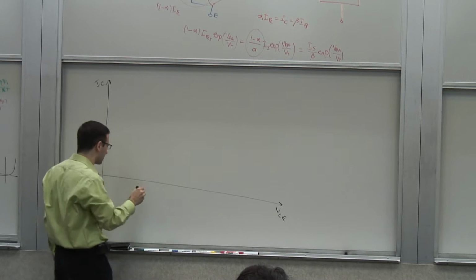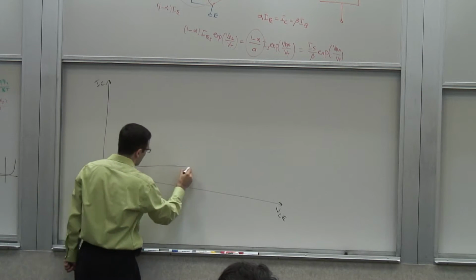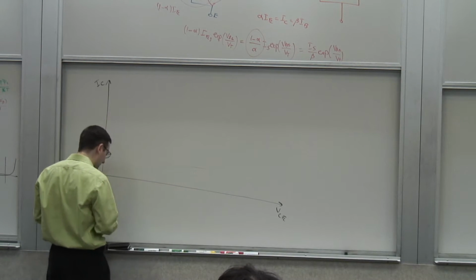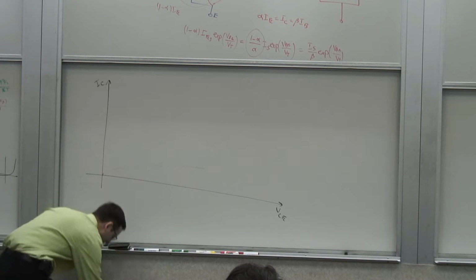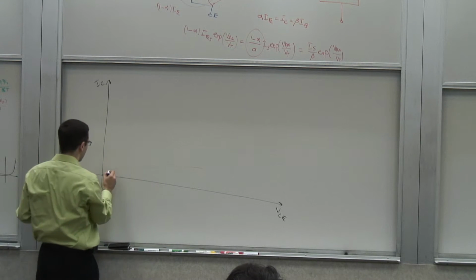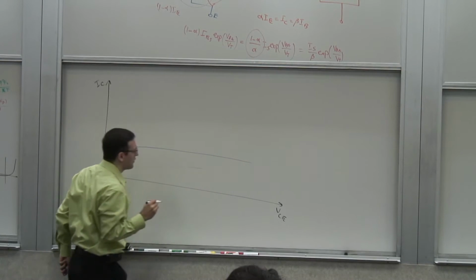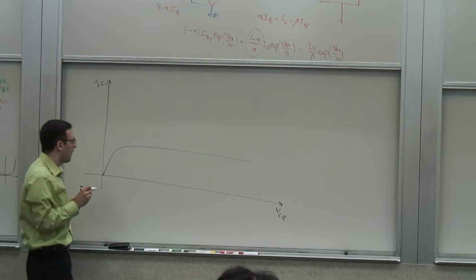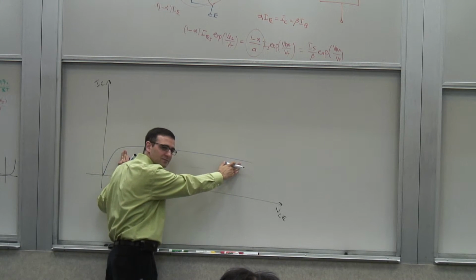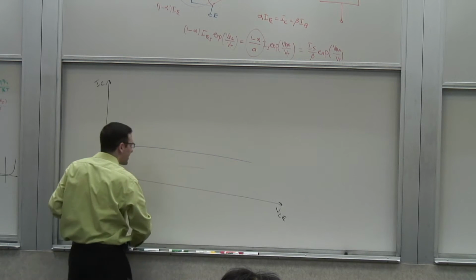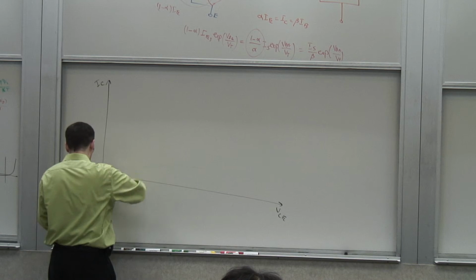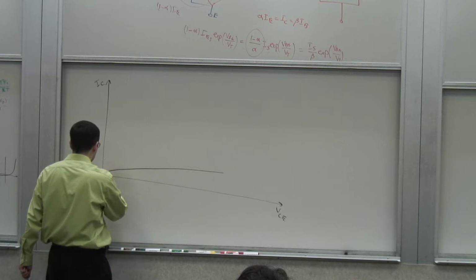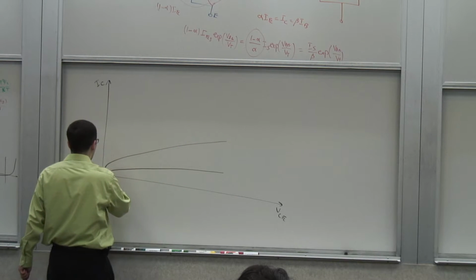for different VBEs, right? So what this picture tells you so far is that you expect for a given VBE to see something like that, right? Now, you want to see a constant current. But when you actually go and measure a transistor, this is not what you see. But you actually see something like this. And these are for different VBEs.